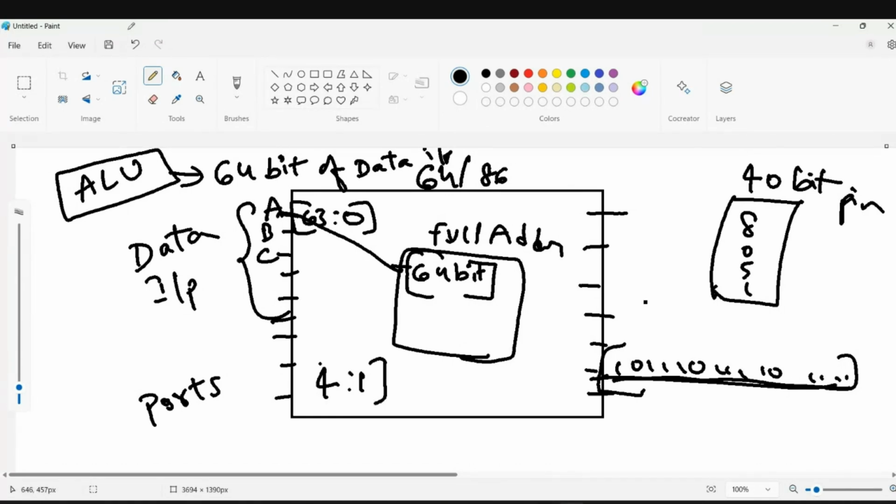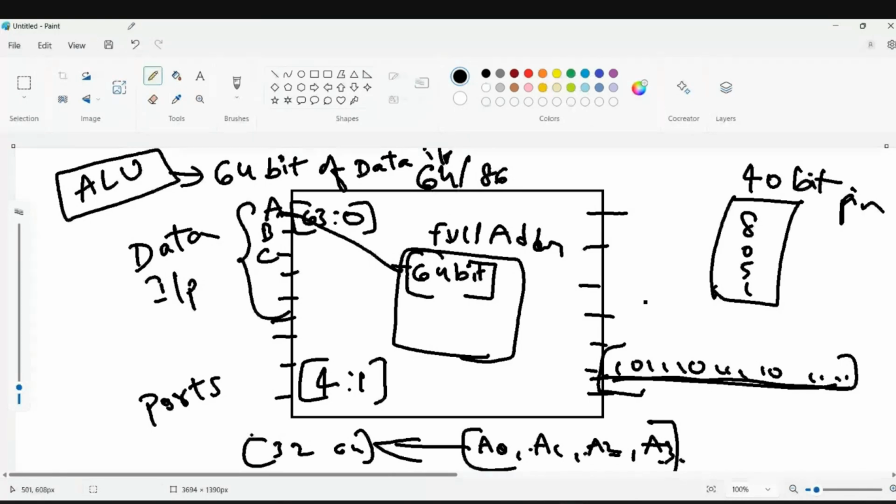Let's say you have a 4 by 1 mux. When you have a 4 by 1 mux, you have A0, A1, A2, A3. This is single-bit data. Still, you can make it a data bus of 32-bit or 64-bit, but you should have registers feeding into A0 to store that data. So when you say 64-bit [63:0], that means you are creating that many registers, that much of a register bank. So A can store up to 64-bit data input. This is your bus range. Is it clear?